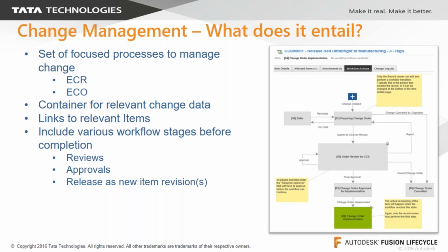And maybe most importantly with change management is that there's a formal workflow, a process flow involved that is tracked. Somebody can make a change request, then it goes through maybe a review process where they determine if the change is going to happen, then it gets assigned to somebody. Finally, when they get done with their work, it goes for a review and it gets approved and then finally released back into a production item, potentially with a new revision. So that's the general concept behind change management.